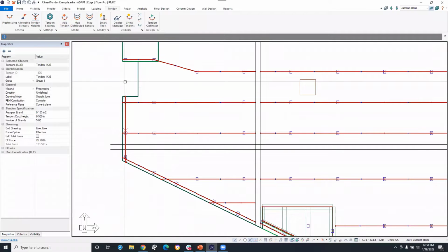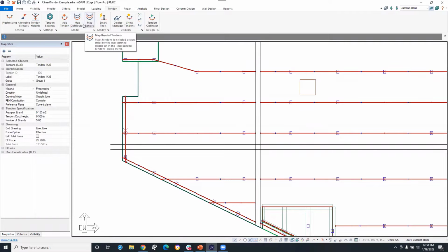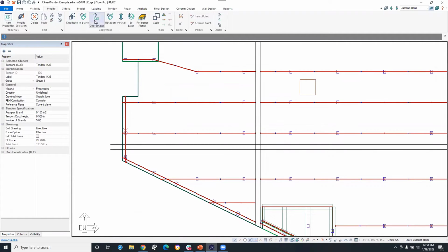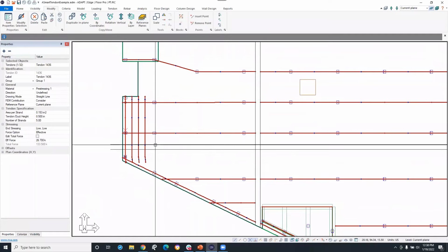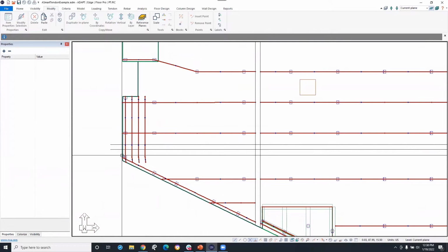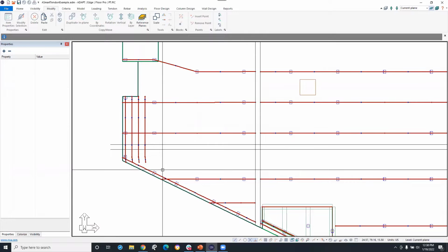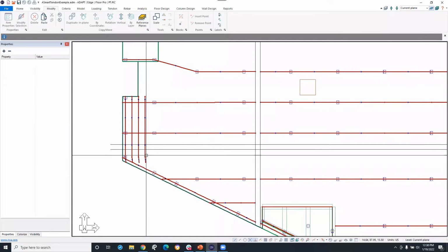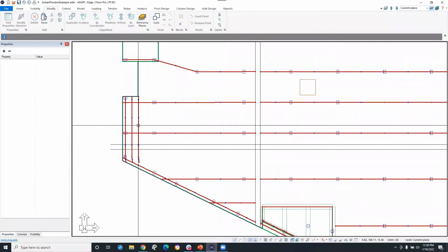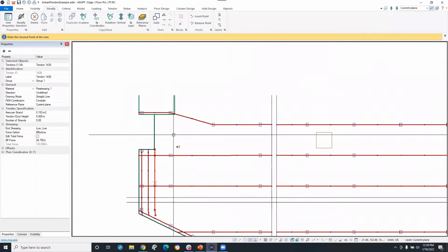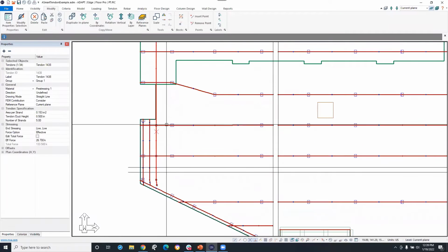I'd then go ahead and grab this tendon, which I'd often call a master tendon, go over to my modify tab, and we can copy this guy, right? Maybe over 4 feet, and we do it, I don't know, 3 times, right? And we've already started to see a problem here, right? This slanted slab edge poses a problem, not a huge problem. Our trim extend tool would typically take care of that. But what I'd have to do now is grab this tendon and move it and do something like this.